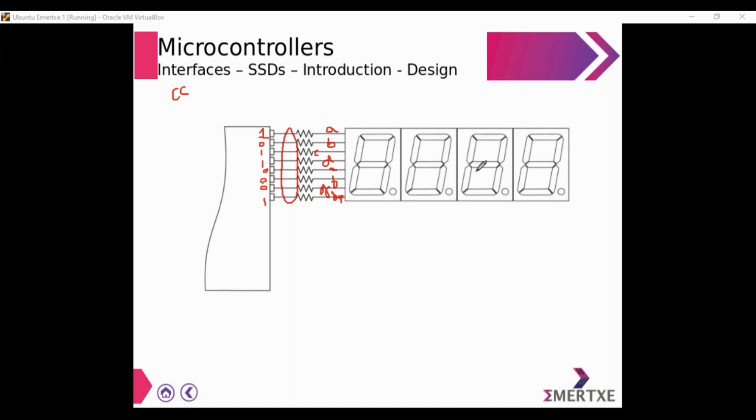Do you think my intention of taking multiple SSDs is to display the same data? No. My intention is obviously to display multiple things at once. So if the hardware connection is made like this, it is going to show the same data on all 4 SSDs.